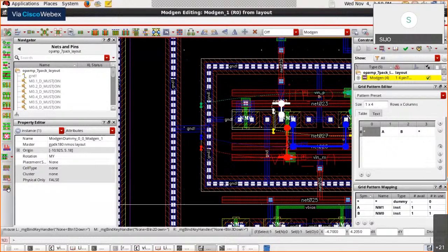But as an analog layout engineer, these tool features will help you get a primary or rough idea about the floor plan or the routing plan, but this will not be an optimized layout as a whole. So the industry practice is always to go by the conventional way. In most of the industry, they will not use any advanced automated stuff for analog layout or custom IC layout, because that will not be an optimized layout.